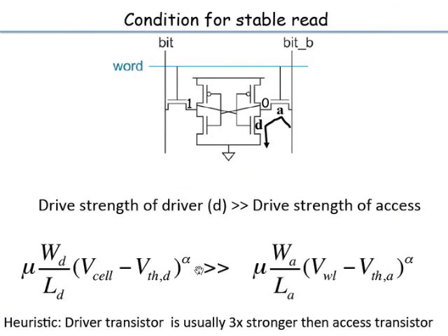1 plus VDS. Similarly, both here, the VDS for this and this is a little different, because when you start off, this has a complete VDD of VDS, because this voltage is VDD, this voltage is 0, whereas this guy's VDS is close to 0. So when you make this much bigger than this, even for a very small VDS, this current will become the same as this current, even though it has a larger VDS. So that is basically the intent of this equation.